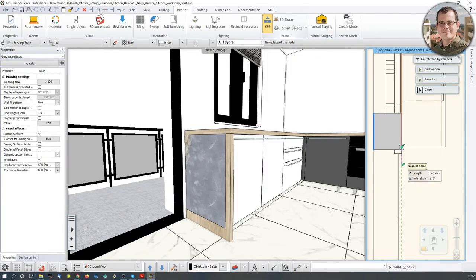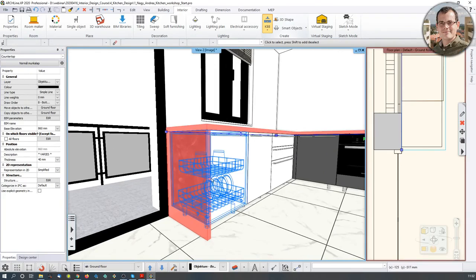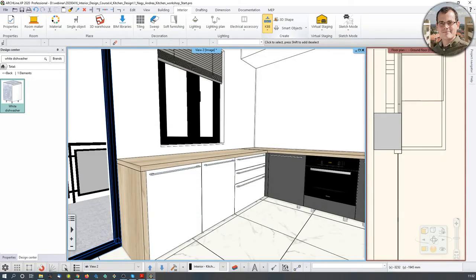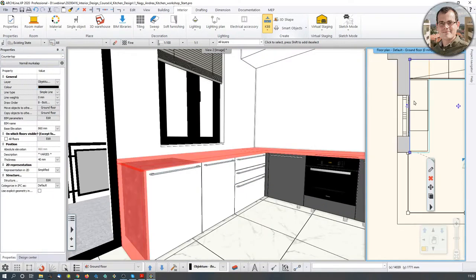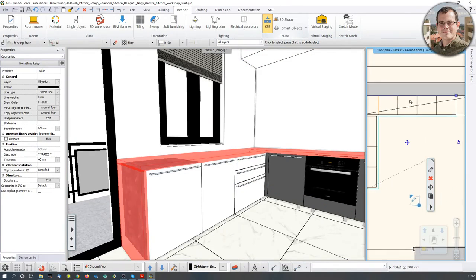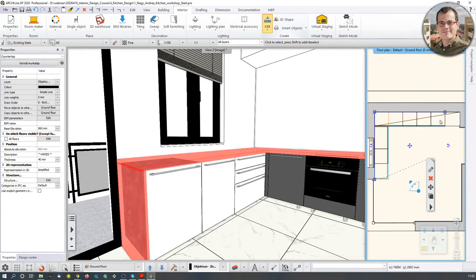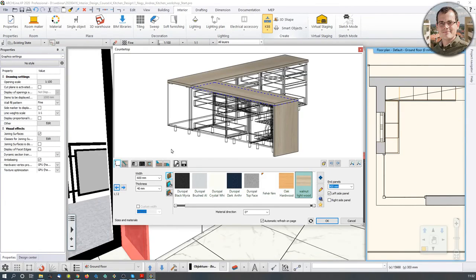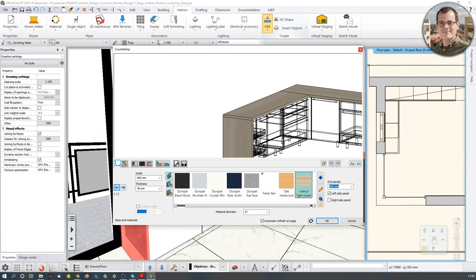How far should I extend it? I think 40 millimeters would be fine because that is the thickness of the panel. So if I say 40 millimeters, then the problem, this bad vibration, is now solved. So that's just a quick reminder. If I click on the cabinet, I'm in the worktop, you can change how the profile or the path looks like. Let's jump back in and deal with other things, mainly a kitchen sink,